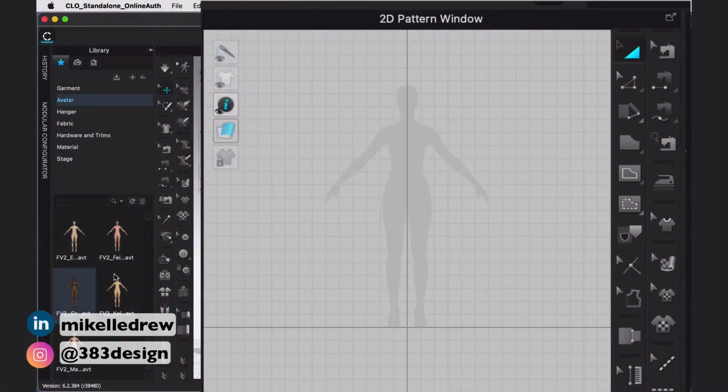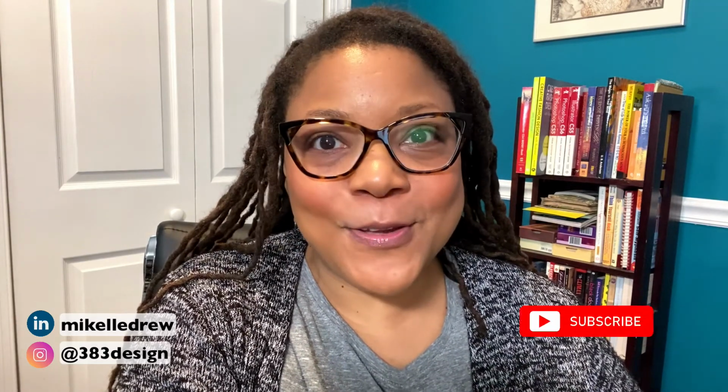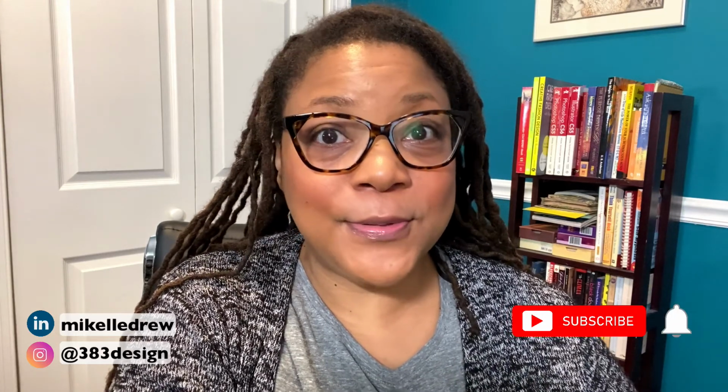Okay, so let me tell you what I like. I like having the avatar reference in the 2D window. Even though you're going to eventually use actual measurements for patterns, it's nice to have that as a reference for how big or small to make shapes. I like that there's only one step to cut and sew the new style line I created. It was like 2 or 3 steps in Browzwear.